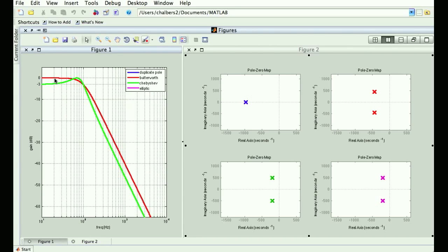And that's what you're getting in this case, right? The green signal does this thing where it dips and it comes back up. So some of your passband frequencies are getting multiplied by 0.707, so they're getting reduced a little bit. And some of your passband frequencies are getting passed perfectly, like at maybe 70 or 80 hertz. So you have some difference in how your passband frequencies are being passed. Now, is that ideal? No. It's not. But it's a trade-off.